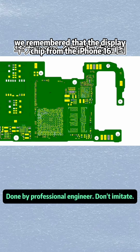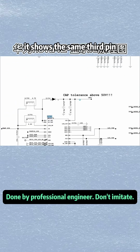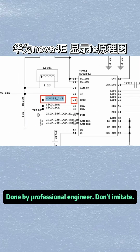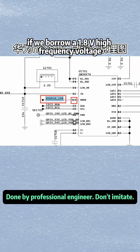We remembered that the display chip from the iPhone 16 has the same function for this pin, so we opened the iPhone 16 schematic. It shows the same third pin, labeled as V_out 1.8V. This means the enable signal is sent from the CPU as a 1.8V high-frequency voltage. If we borrow a 1.8V high-frequency voltage, it might work.